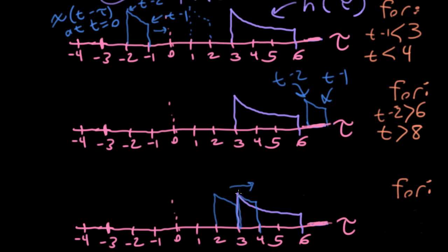Eventually, we'll hit a point where the left edge of the blue block matches the left edge of the purple block, and when it keeps moving right, we'll then enter what we'll call a total overlap stage. So in general, we'll actually have something in between these 2 points, and let me illustrate that by drawing it, say, going from 2.5 up to 3.5. Oh, I should notice I don't really actually have these 2 vertical scales very well. The blue block goes from 2 down to 1, and the decaying exponential actually starts at 1 and then decays. I think that's okay here because we're really only needing these graphs to figure out what the quote-unquote overlap is in the horizontal dimension and the tau dimension.